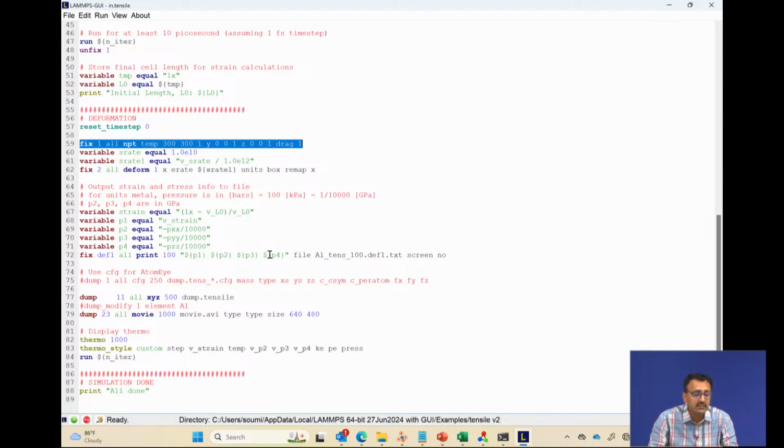So you might be thinking, and then see a question that, what thermostat and barostat are you specifying? The default thermostat in LAMMPS is the Nose-Hoover, which is very, very popular. It captures the added term to the Hamiltonian in a pretty accurate manner, but you can choose other more recent thermostats. For example, the Bussi thermostat is very popular as well. It's a velocity scaling thermostat that is stochastic. As far as the barostat goes, the default one is called the Parrinello-Rahman barostat. Again, it's been around for a while. But you have options of using other thermostats and barostats for other applications.